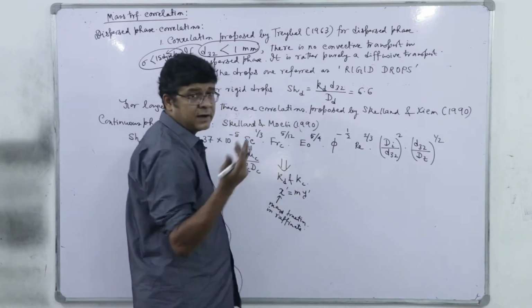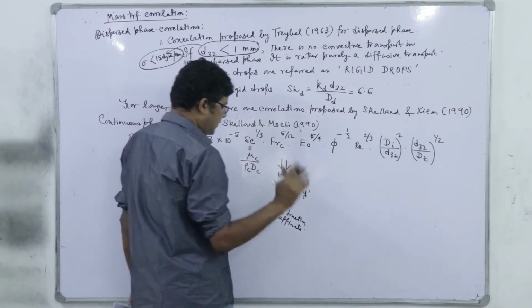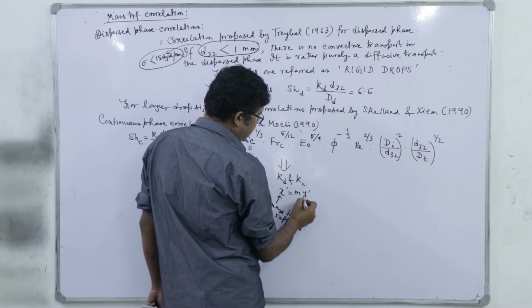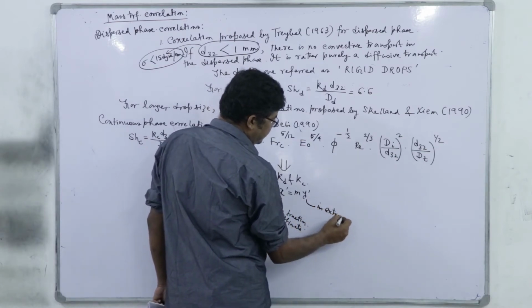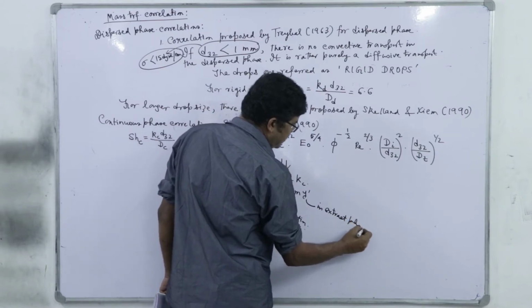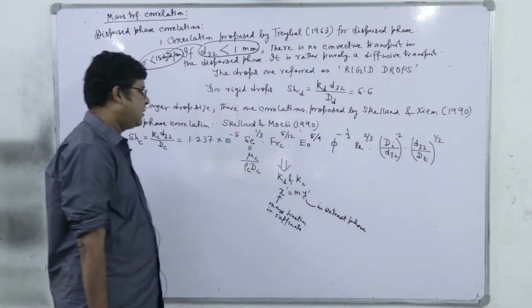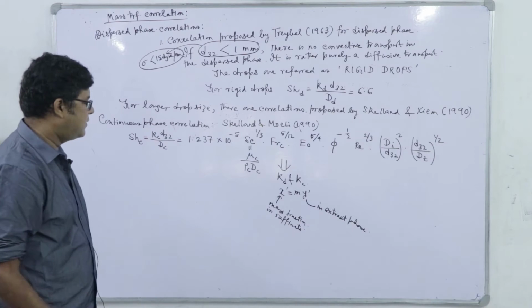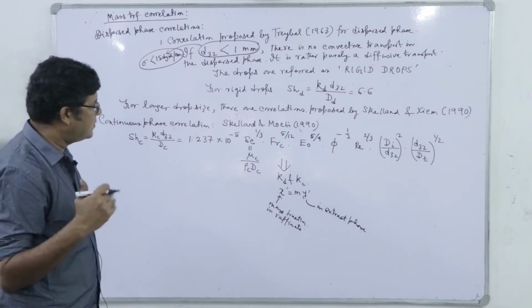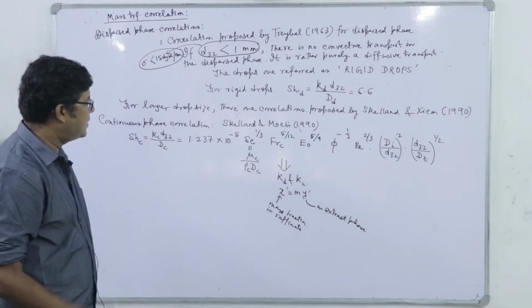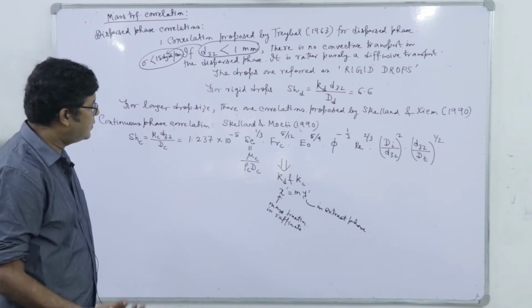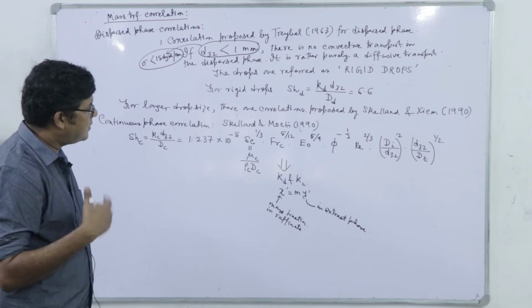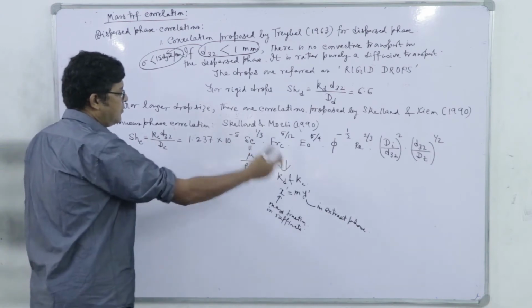You have to choose which one is raffinate and which one is extract. Now, generally, though it is not a universal rule, the dispersed phase is the solvent and the continuous phase is the solute or carrier. It may be reverse and accordingly we have to change.